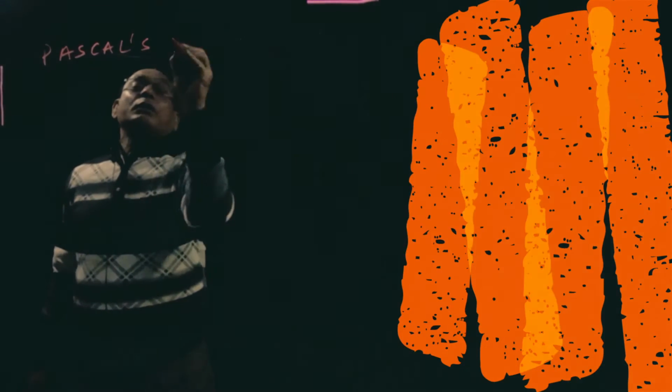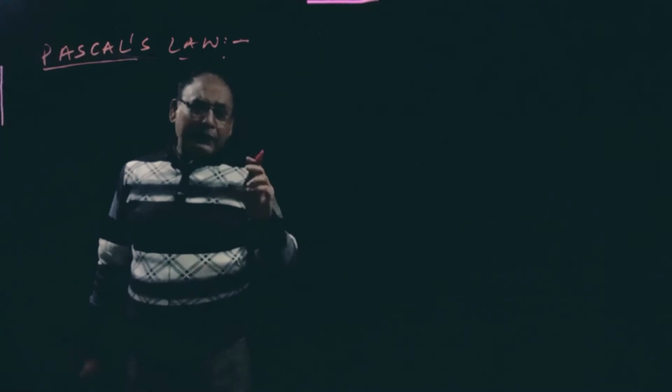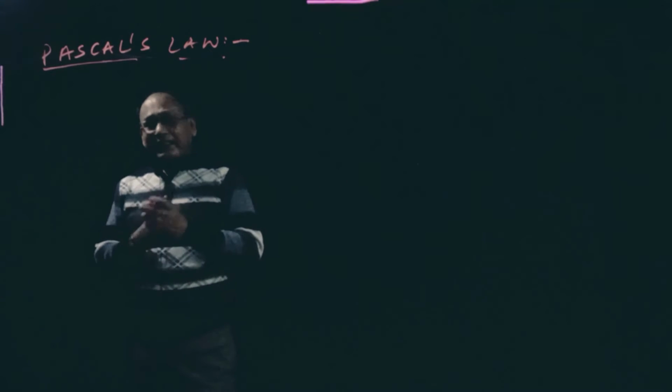Now I am going to derive Pascal's law. What is Pascal's law? It is also about fluid statics only. Suppose there is a fluid; at a particular depth, at a particular point, the intensity of pressure will be equal in all directions, whether it is in the x direction, the y direction, or the z direction. All intensity of pressure will be the same. That is the statement of Pascal's law.